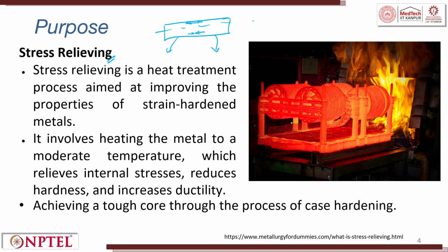I do stress relieving. Stress relieving is a heat treatment process aimed at improving the properties of strain hardened metals. It involves heating the metal to a moderate temperature, which relieves the internal stresses, reduces hardness and increases ductility. Achieving a tough core through the process of case hardening is also possible, wherein only the surface is hardened, not through and through.